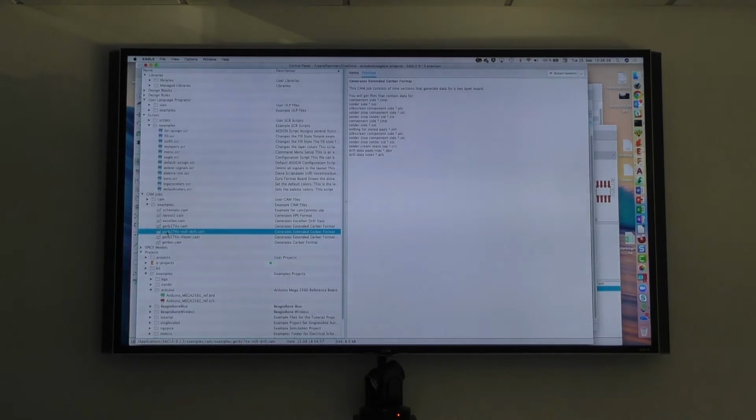So I have to produce a set of Gerber files, and I need silkscreen, the print. I need solder paste for the assembly components for top and for bottom. I may have some cutouts in the board, milling contours, something like this. So I have to create 10, 15, depending on the board, Gerber files, and so we automate this with the CAM jobs.